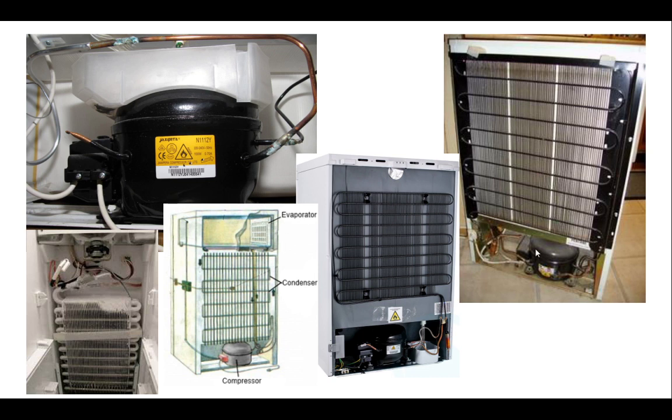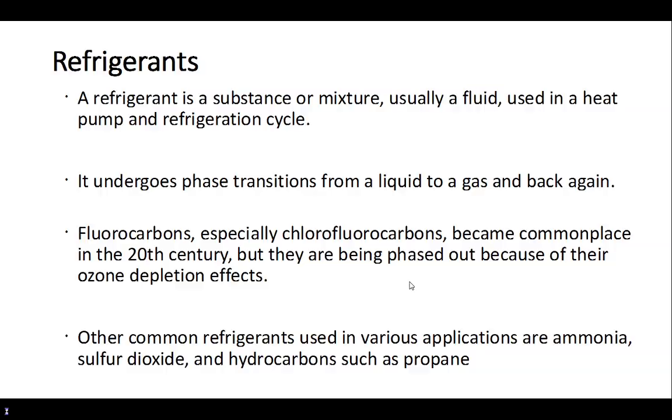If things go wrong with the fridge, it's either that the refrigerant is no longer enough in there, so it's been leaking out, or there isn't enough air for the condenser to get rid of the energy of the heat which is produced. Could be an electrical fault with the compressor, or it could just be that the pump is worn out. The compressor is just a pump, really. It's nothing else.